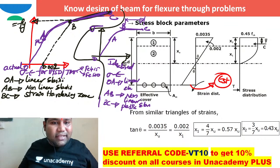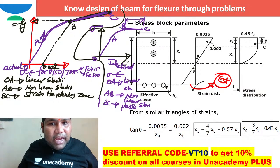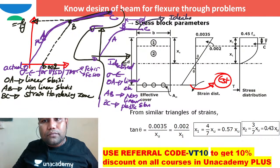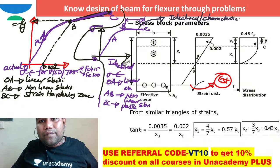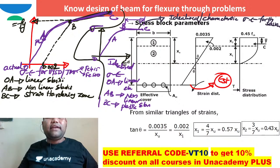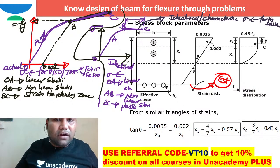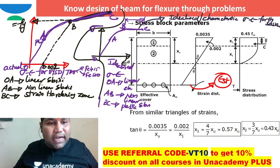So how can you get the design stress strain curve for HYSD steel? This is the idealized or characteristic stress strain curve for HYSD steel. How will you get the design stress strain curve? Characteristic stress strain curve divided by the factor of safety. So can I do that here?